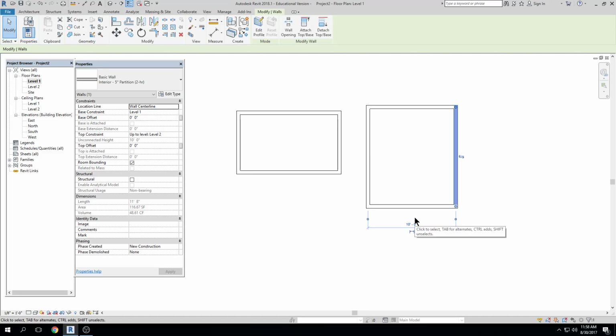Another thing that's a little bit different in Revit than AutoCAD, and it's said in the name, Revit is short for revise it, right? I feel like when you draw, you don't always draw things the exact right size the first time. Sounds very counterintuitive when you've drawn in AutoCAD, because in AutoCAD you want to get it right the first time, right? It's the right size. But in Revit you generally will get things in the right spot, you'll generally get them the right size, then you will revise them to how you want them to be, okay? And the same thing applies to creating objects. So when I want to create a brand new wall type in Revit, I don't just click on the new wall type button.